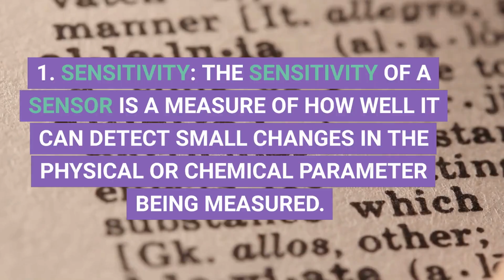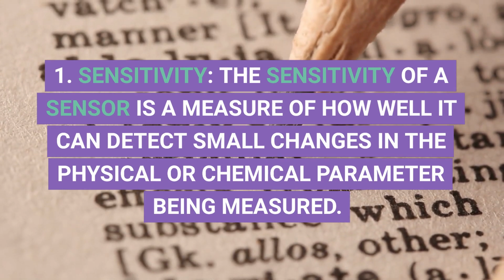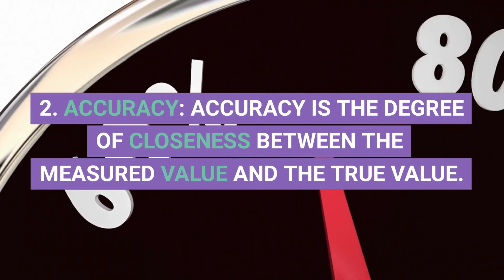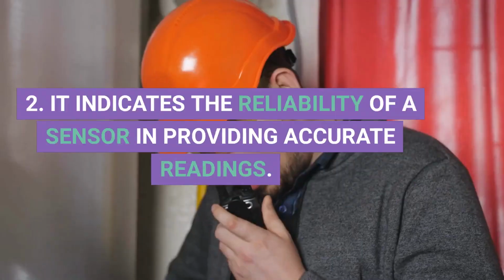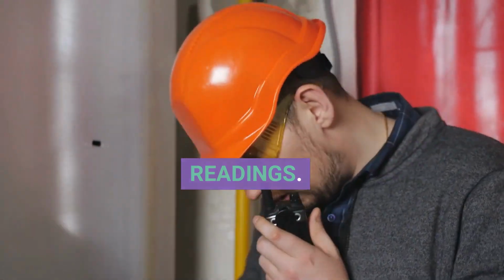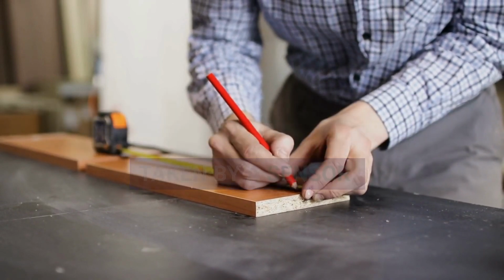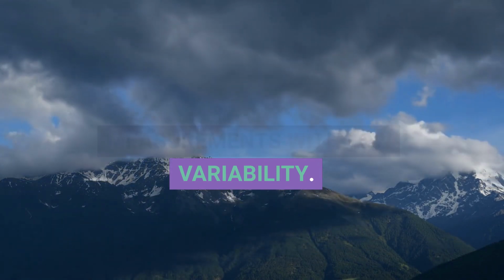Sensor features. 1. Sensitivity. The sensitivity of a sensor is a measure of how well it can detect small changes in the physical or chemical parameter being measured. 2. Accuracy. Accuracy is the degree of closeness between the measured value and the true value. It indicates the reliability of a sensor in providing accurate readings. 3. Precision. Precision is the degree of consistency in measurements taken by a sensor. A highly precise sensor produces measurements with low variability.